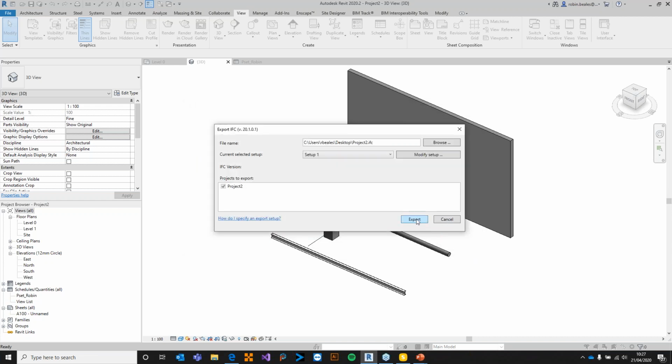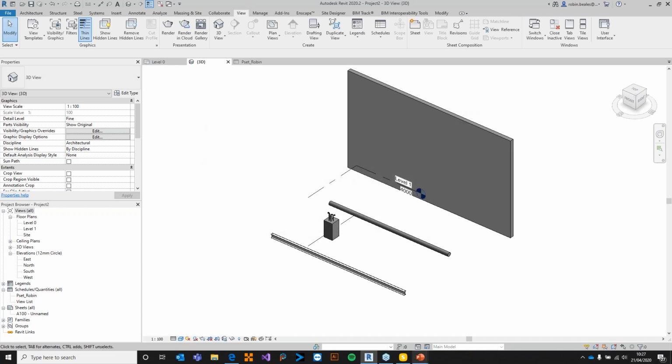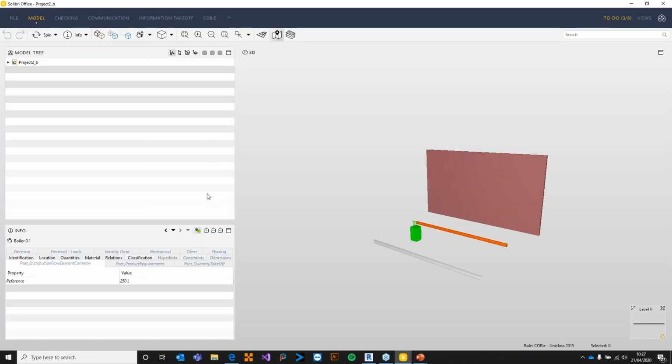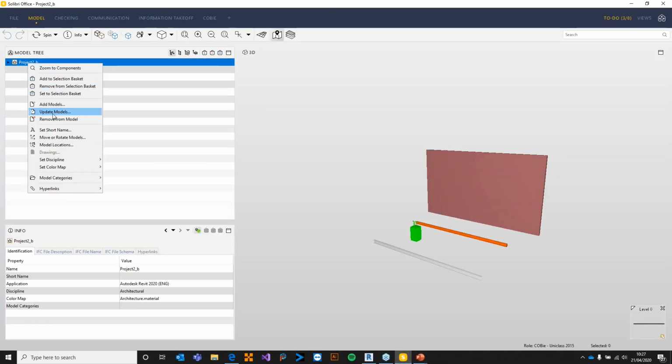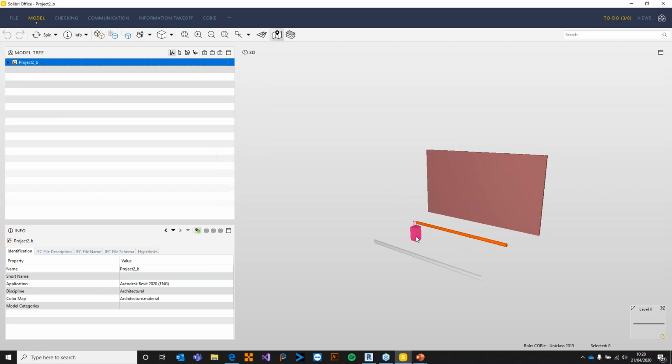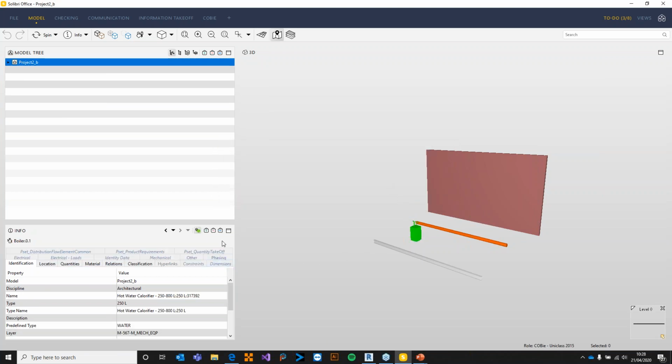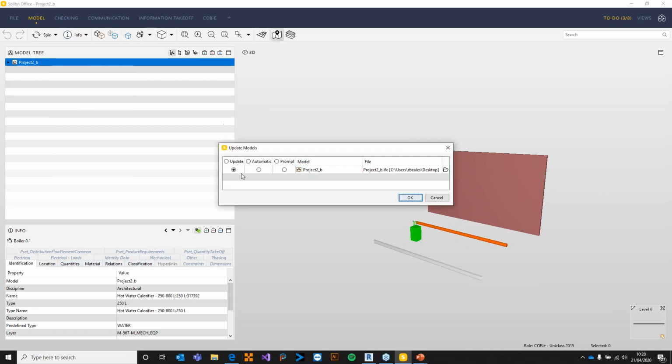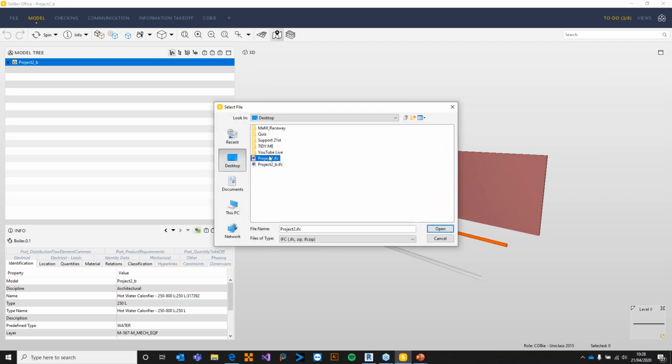That way, I have complete control through a visible, editable, usable Revit schedule over what objects have what properties in the model, and when I get across into my IFC, if this is required or relevant, I can then have a very specific property set against... make sure I open the right IFC would be good.